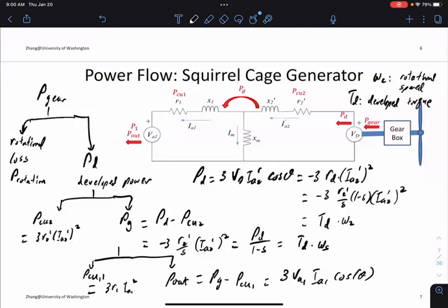So here, this is a complete flow of active power. Reactive power is whatever it is, because the reason we don't talk about reactive power here is we have no control. All we can do is put a negative resistor in the system, and that has nothing to do with reactive power. We can't get reactive power out of it. So reactive power for this kind of calculation just is what it is. We have no control.